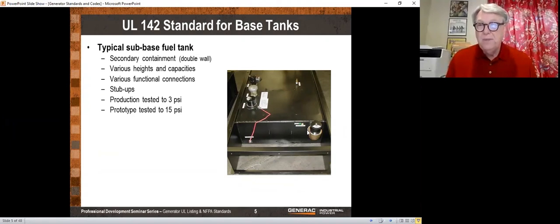Right here on the very end, in the more on the top, that's called your emergency vent. Emergency vents are not required. They are optional, but they are required on an emergency generator. And so it's important that the manufacturer of your generator know that it's going to be an emergency generator so that they can apply those to the tank, because that's a requirement that exists there.